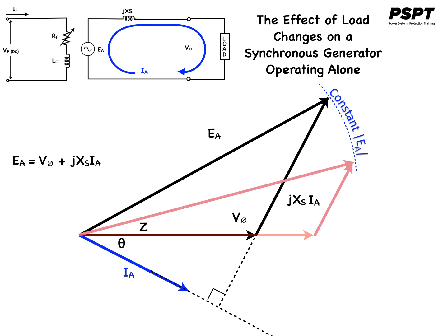If the constraints are observed, then it is seen that as the load increases, the voltage V phi decreases rather sharply, as we see here, compared to the original load before the increase. And EA has remained constrained as far as its magnitude is concerned.